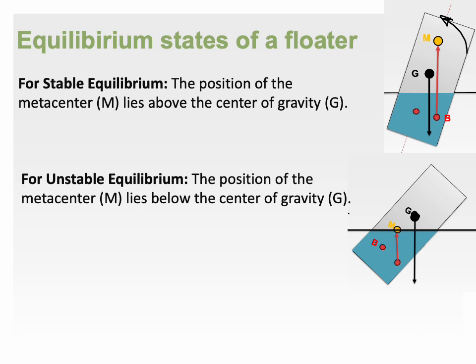When the object is tilted, in this case, the buoyant force generates a moment that further increases the tilt, causing the object to capsize even more.